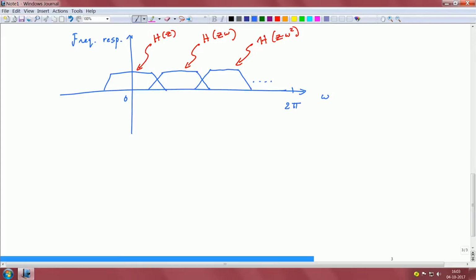So, now we know the criterion that we would want some filter h of z to satisfy if the sum of frequency responses has to be 1. That means one such filter could be the Nyquist M filter, which is of the form c plus delay times the polyphase version plus 2 units of delay followed by the second polyphase, dot dot dot. Okay.